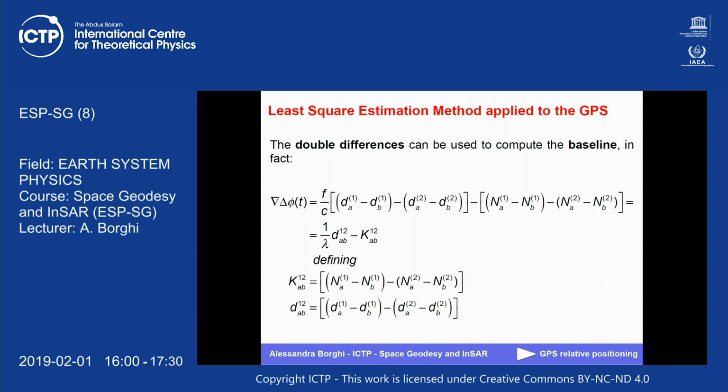We have already seen that when we speak about double differences, it means that we compute the component of a baseline, a vector connecting two receivers. And at the end of the analysis, we are going to estimate these components, in fact.